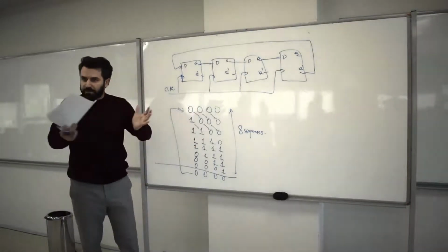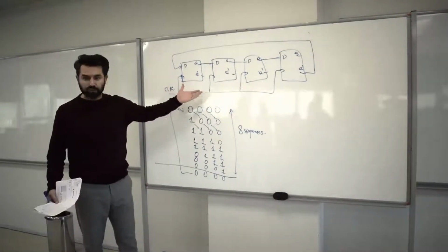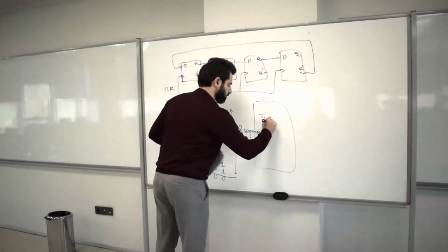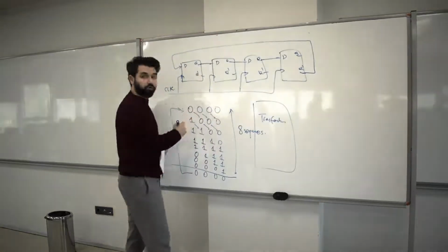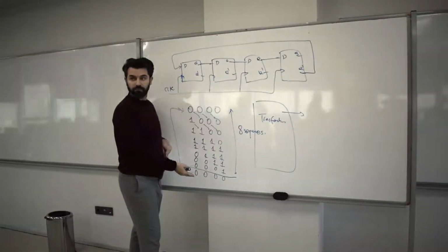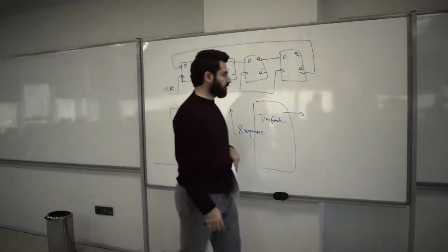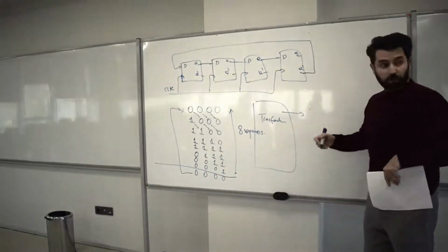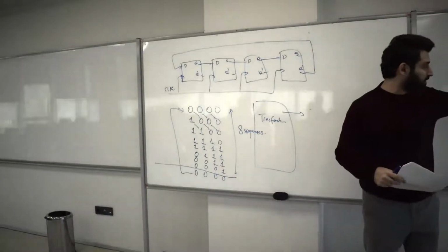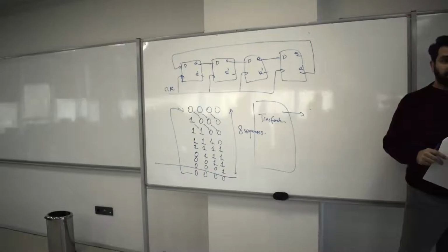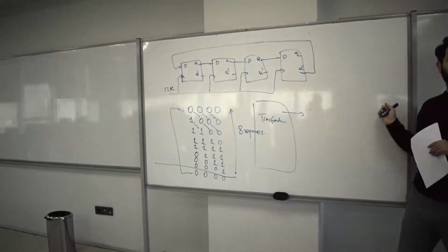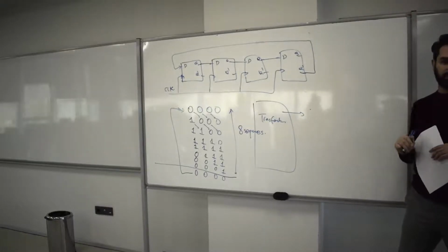If you would like to expand the number of possibilities at the output to 8, then you have to use some kind of transformation to generate this sequence, since there are 8 of them, right? So these are 8 sequences. So in order to generate the format that I just described, I have to have 8 bits, right? Because the format here implies that there are 4 bits, that means there are 4 sequences. Okay, perfect, bingo. I have 8 sequences, then I have to have 8 bits. And only 1 at a time, one of them can be logical 1, the rest of them are zeros.